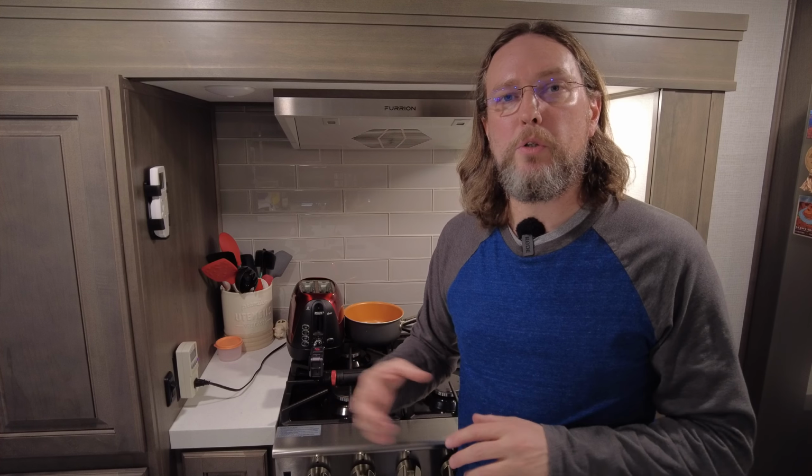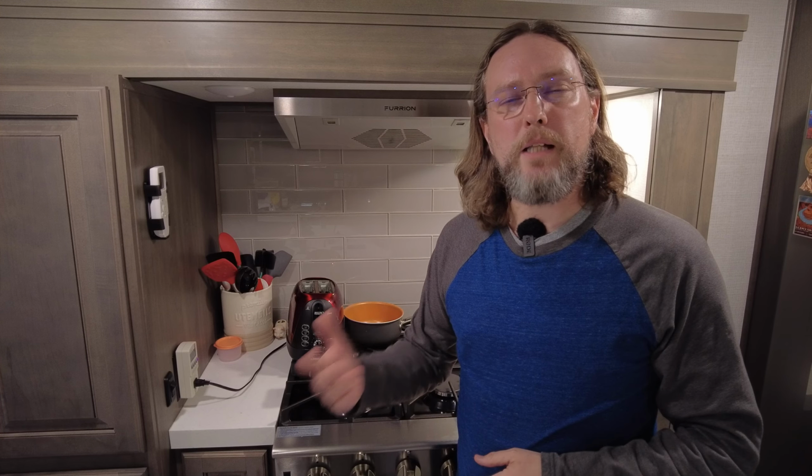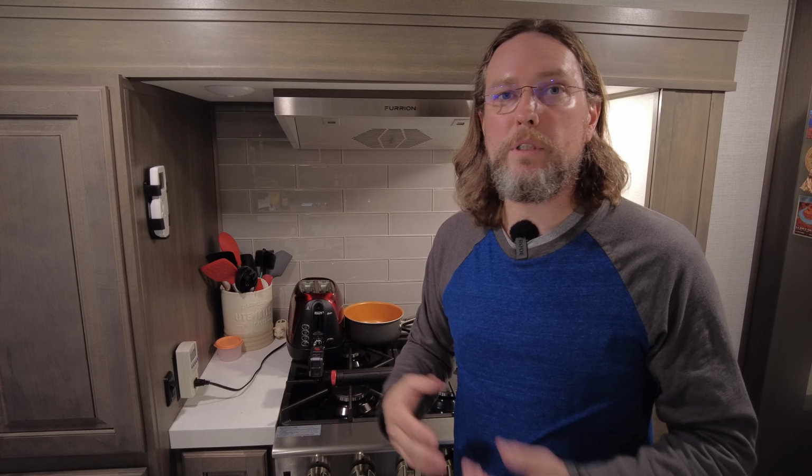But again, that just goes to my point about not relying fully on those label plates, because they may not be entirely accurate when you buy the appliance or gadget brand new, and over time they may deteriorate and draw more or less power. So using one of these little plug-in watt meters is great to understand how much power these items draw that simply plug into a 120 volt outlet.